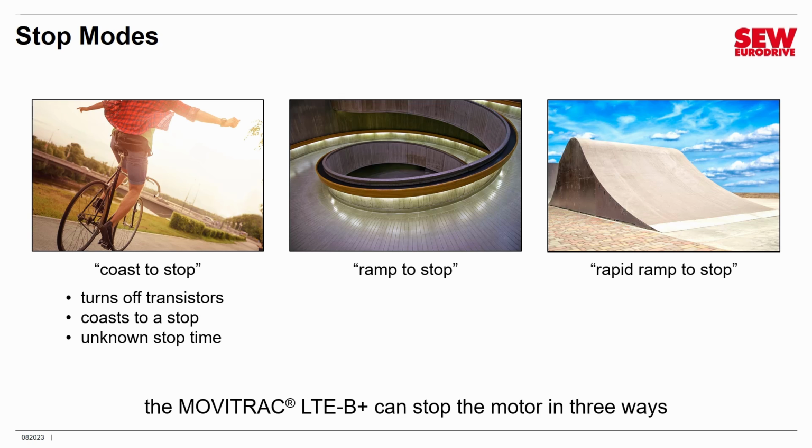The VFD just cuts off the power transistors, and then it just waits for the motor to come to a stop on its own. Now, this might happen very quickly. If the motor doesn't have a huge load on it, probably friction will bring it to a stop in just a few seconds. On the other hand, if you've got a very large load with a lot of momentum, that motor may turn for a long time before things come to a halt.